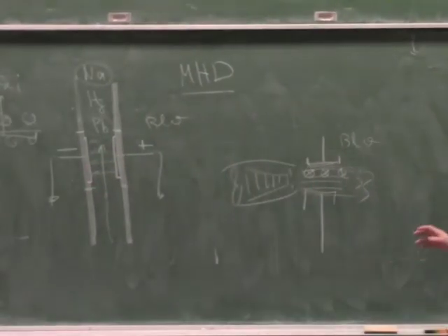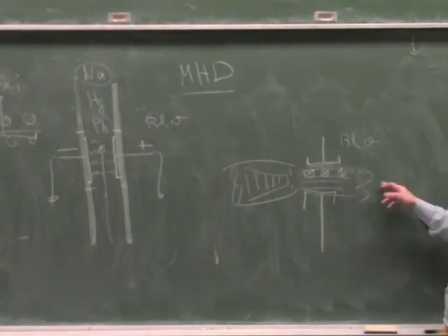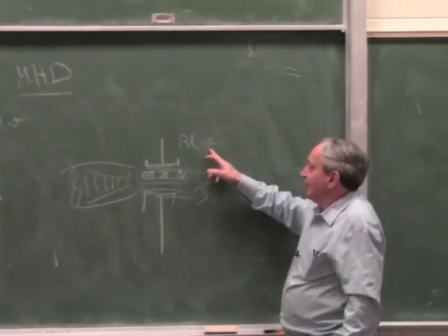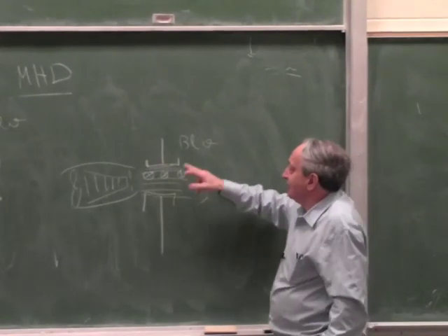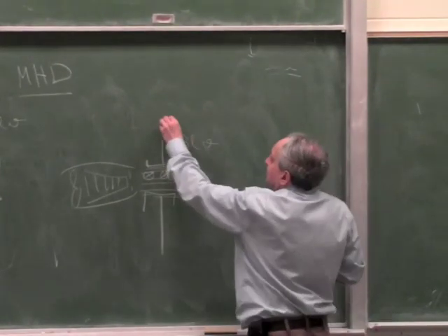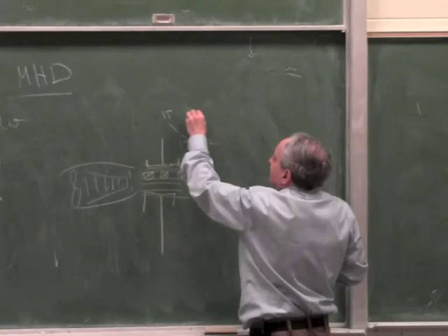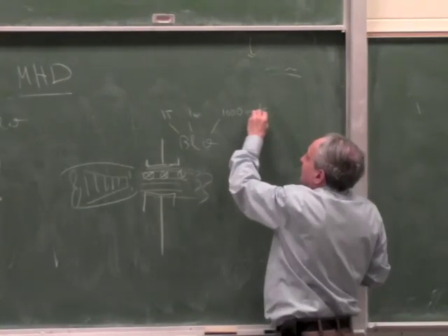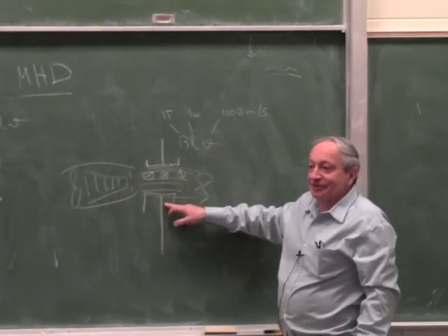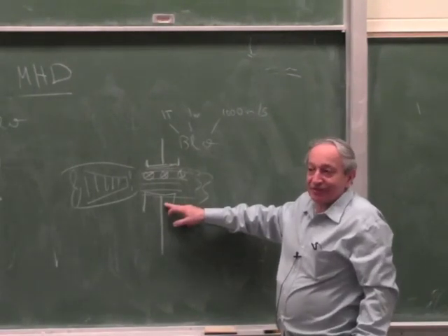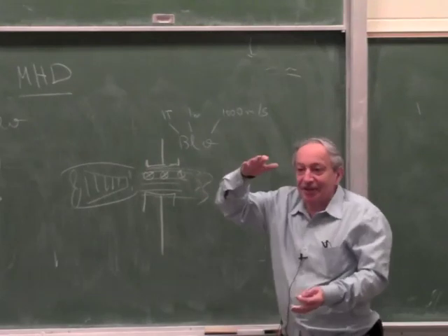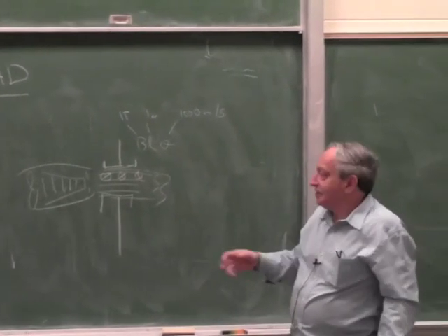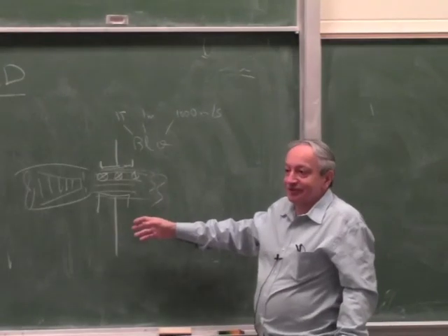But here, this comes out, could come out at the speed of sound. Okay? So V is very high, so even if L is 1 meter, say this is 1 Tesla, this is 1 meter, but this is 1,000 meters per second, you'll get 1,000 volts. It sounds very attractive. And the electrodes can be very big, you can get like an amp at 1,000 volts, sounds good. So this is an MHD generator.